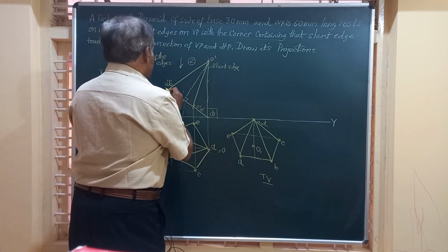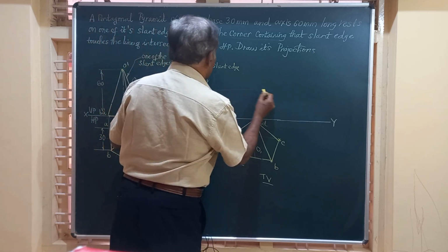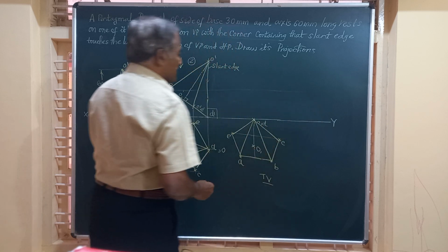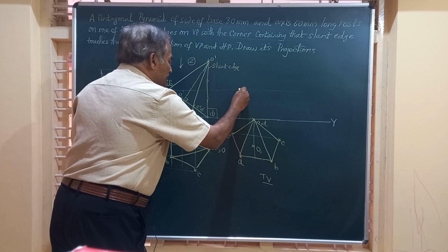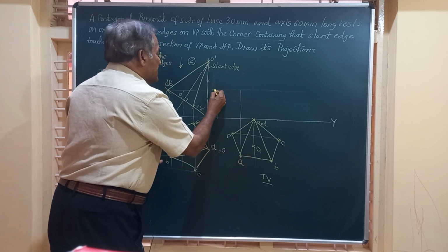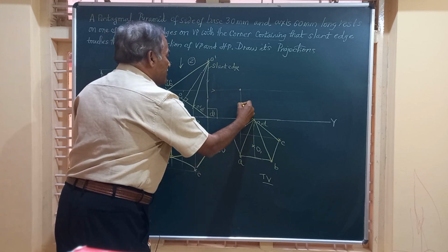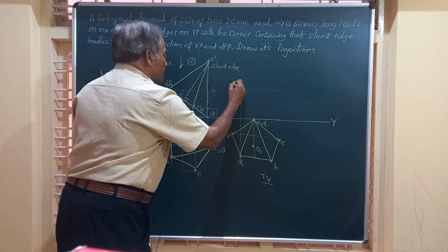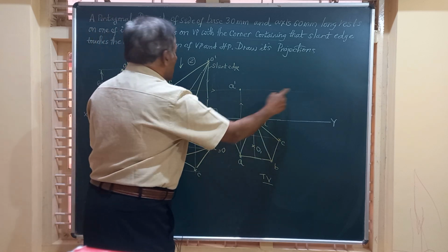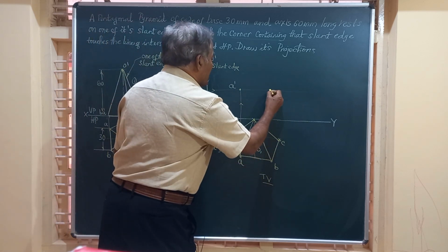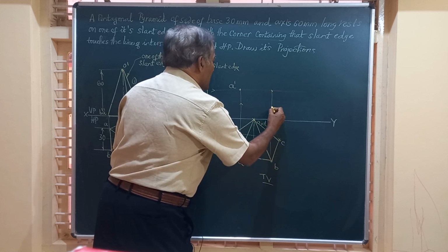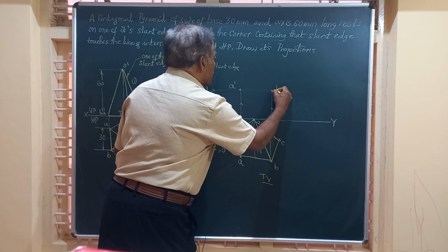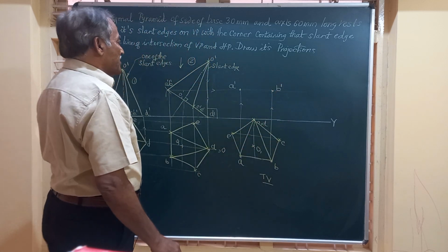Okay, on this line A dash B dash drawn horizontal, the points A and B will lie. So I will write a vertical line from here, a horizontal line from here. The point where those two intersect is our point A dash. On the same line, write a horizontal from B dash, a vertical from B. Friends, this will become the point of intersection and this will give you the point B dash. You have got A dash, you have got B dash.